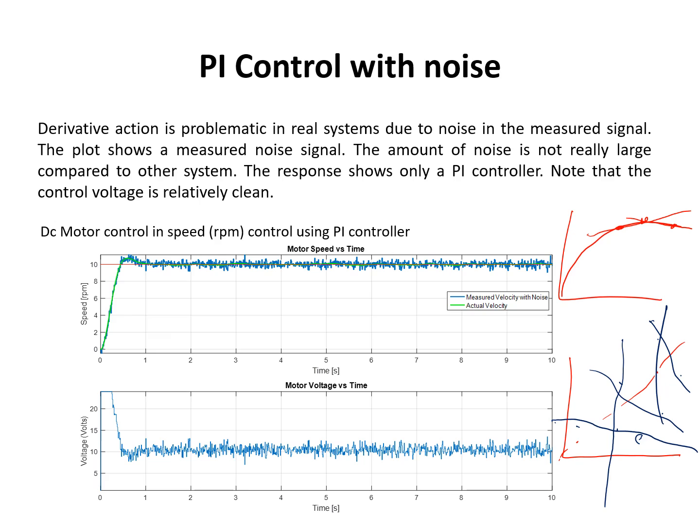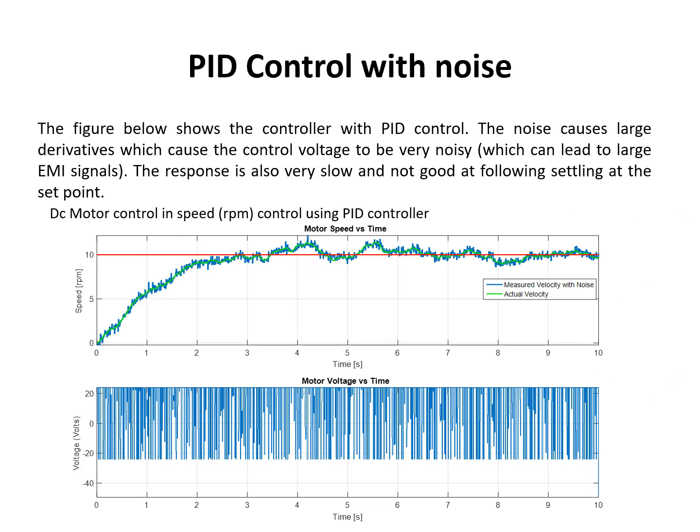So again, in any sort of system where you have noise on your measurements, adding derivative control typically gives a much noisier output simply because the derivative is noisy. This is highlighted over here. I've taken the exact same controller, just added derivative control, and where the system responded previously with our PI controller something like this, we now have a much noisier response. Our output is quite bad, and we can see the voltage we supply to the motor basically goes between our maximum -24 and 24 volts.